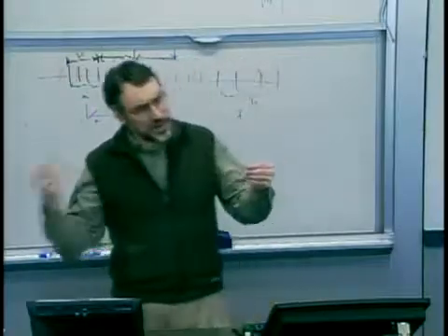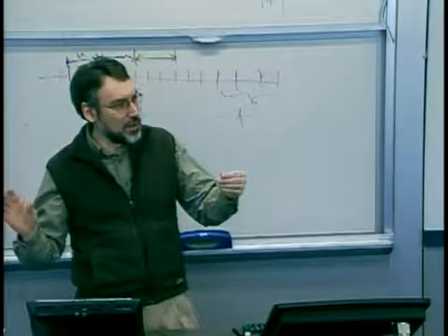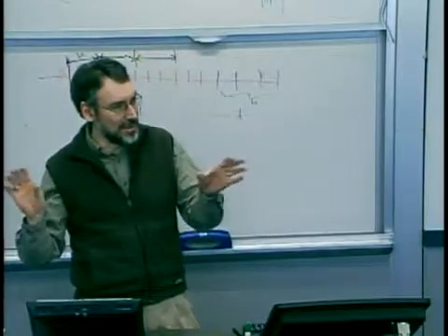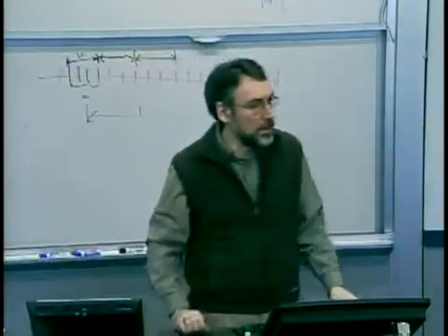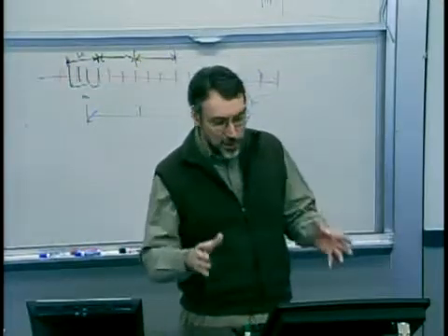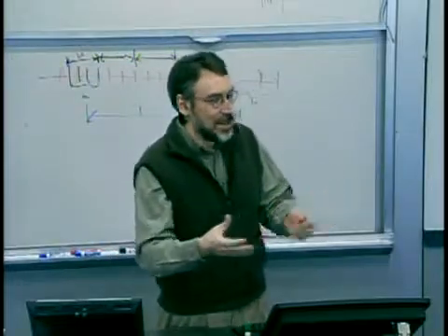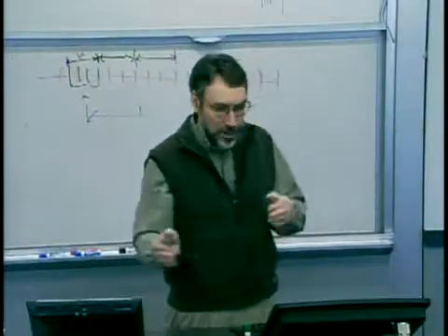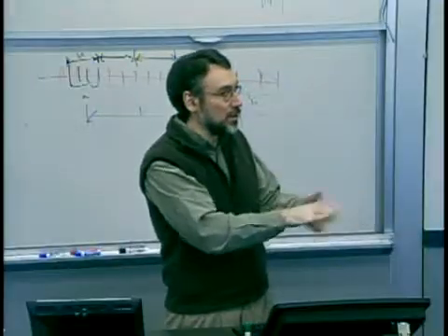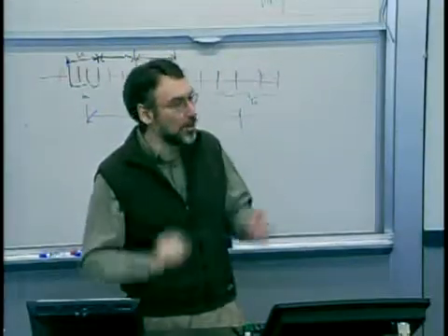I might also still care about, say, channel length, and so I might have another chart on that too. I have to be careful because they're not completely independent. But what you really want to do is get your statistical process control apparatus targeted at or applied to the things that are most critical to you. And so in your scenario, the tracking between those two parameters, that's what I would monitor.